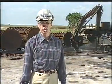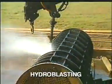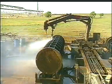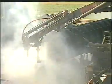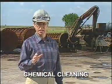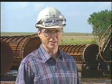After fouling has occurred, removal methods depend on the type and severity of the deposits. Deposits on the outside of tubes can often be removed by hydroblasting, a high-pressure stream of water that loosens and washes away the deposits. Streams of water or steam can also move the deposits from the inside of a tube. If water and steam fail, chemical cleaning may dissolve the deposits. If, however, the deposits resist both chemical cleaning and hydroblasting, the exchanger must be completely dismantled and the deposits scraped off. At this point, it may be best to retube the exchanger.